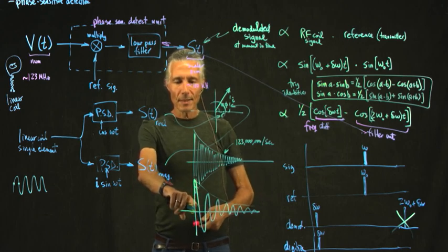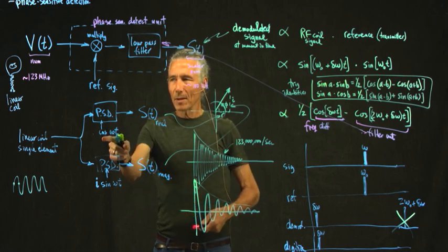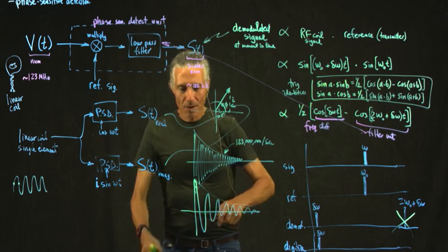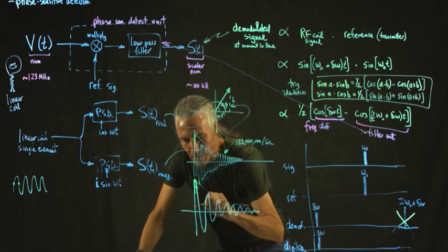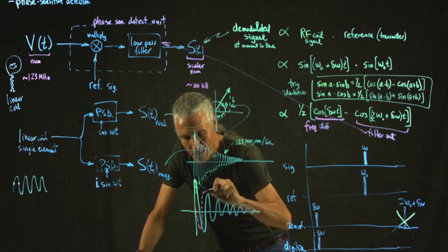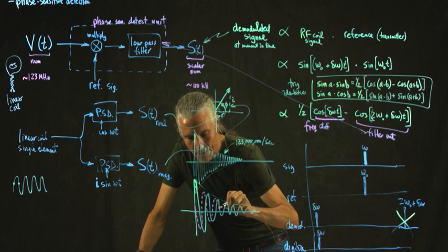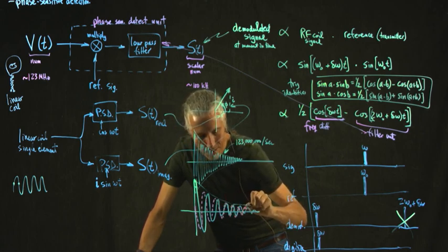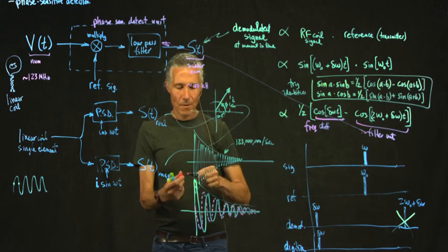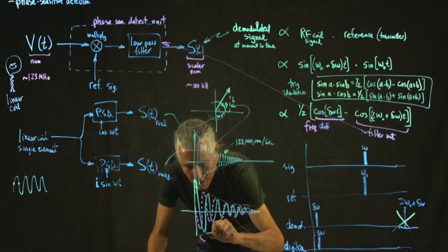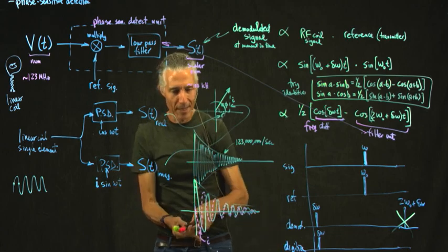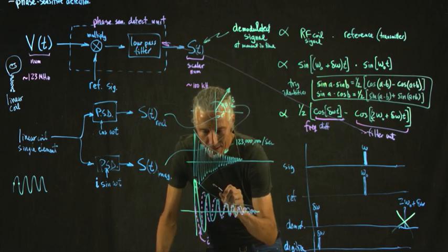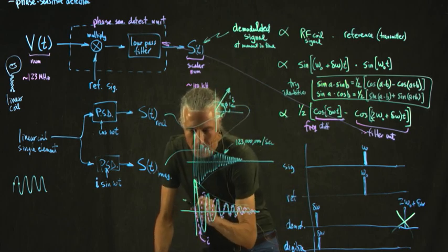If that was the real part that came out of multiplying by a cosine, it's also going to have another set of numbers coming out of it that's multiplying by a sine. I'm not drawing it very accurately, but this one is the imaginary part of the signal, which you get by multiplying by the sine, and this one is the real part of the signal.